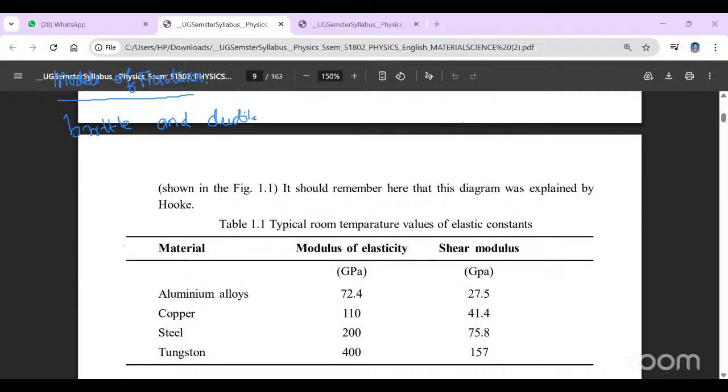The surface of a metal has higher energy than the interior planes. Moreover, at the surface, the atoms do not have as many neighbors as in the interior, and therefore they form only a few bonds. The interior atomic bonds can easily be destroyed by means of normal stress. Since brittle fracture does not produce plastic deformation, it requires less energy than a ductile fracture.